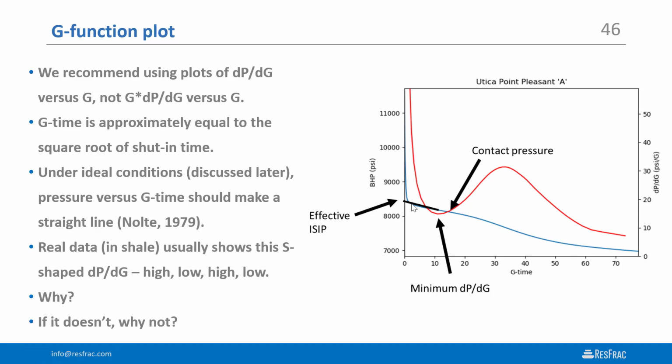Even if it's full of water, which is pretty incompressible, that still could be a couple barrels of fluid that's released from wellbore storage after shut-in. So you might have a couple barrels of water flowing into the fracture after shut-in. And that's why it takes a little while for this pressure gradient to dissipate. But over time, that pressure gradient is going down, the flow rate's going down.